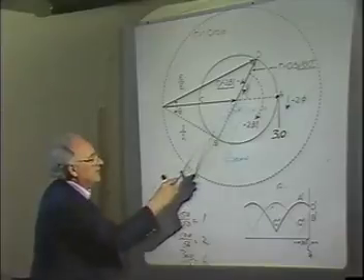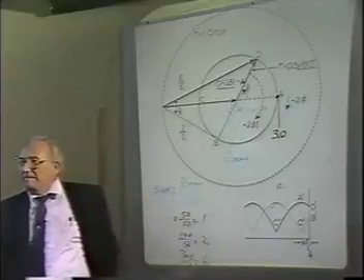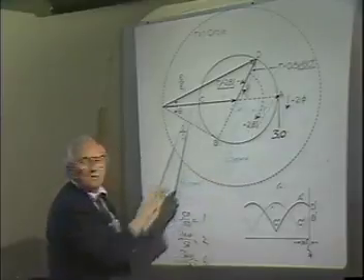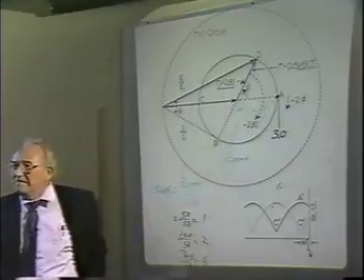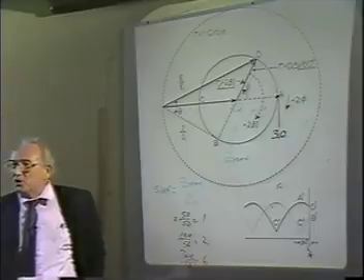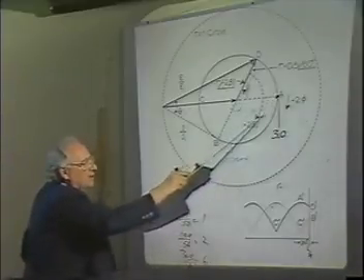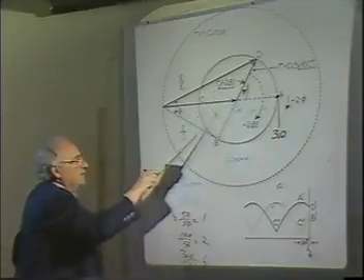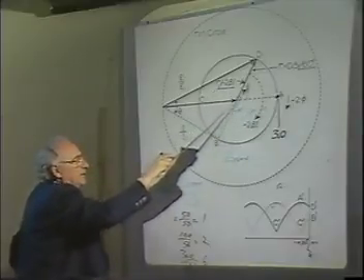And it's on the other side of Z max, isn't it? Exactly the same distance away as Z max is over here, Z min will be over here if there's no loss on the line. If there's a loss on the line, you know as you go back toward the generator, what happens to this? It would spiral in. What happens if you keep going back further and further on the lossy line?